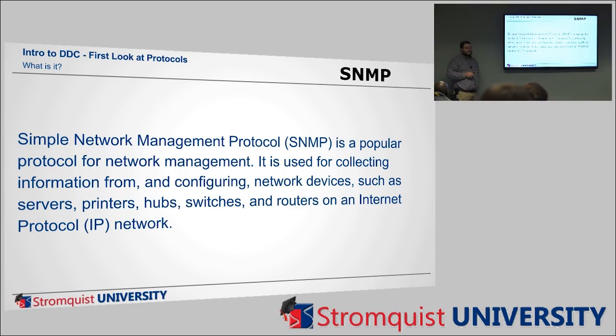They have gateways, and this is common. I've got a BACnet bus in my system. My front end, my Jace, is on this floor, and I'm talking about 3 floors up. For me to run another wire from that device all the way down is not feasible. So they have gateways or converters. I've got a new burner controller on my boiler that I want to pull some more data off of. I can put a gateway in, which converts the Modbus to BACnet. You've got to buy another piece of hardware, but sometimes that's more cost effective than running a new bus throughout the building.